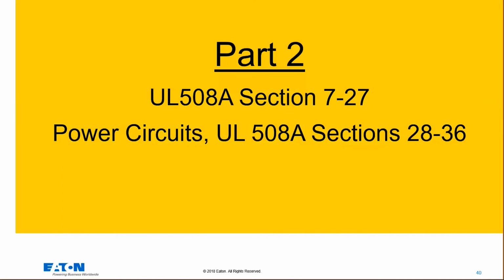It's rare that you'll see a particular brand spelled out unless you're talking about breakers for the most part, because in the breaker world, they're going to spell out a particular breaker to be used ahead of it, because not all breakers are made the same, and there are no real umbrella ratings that you would have in the fuse world.